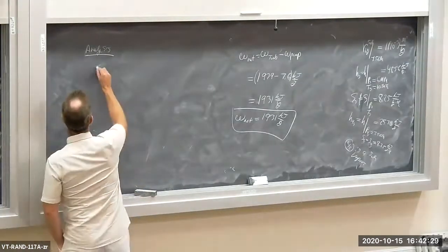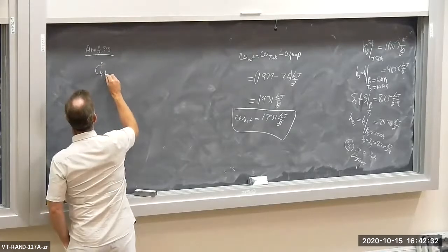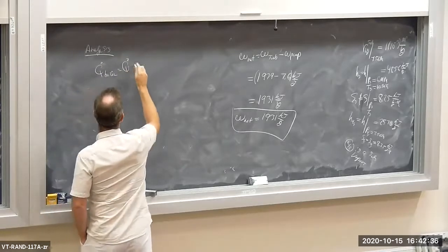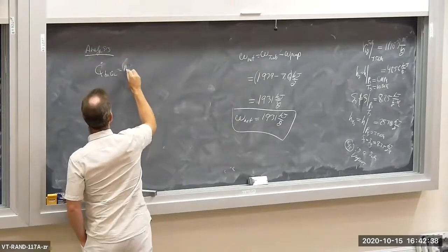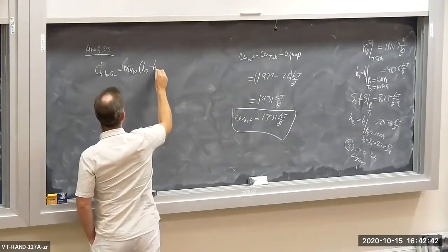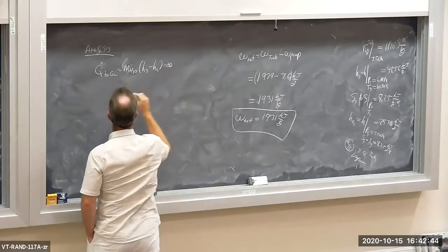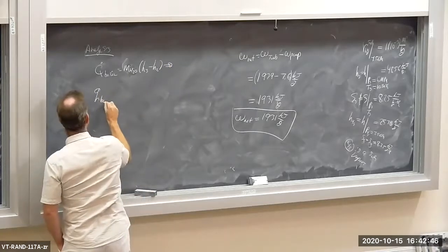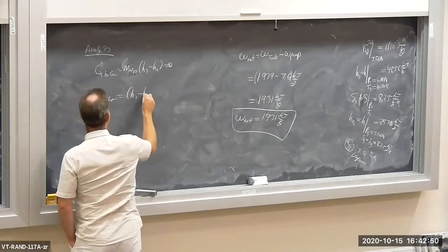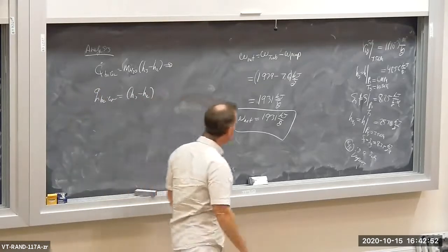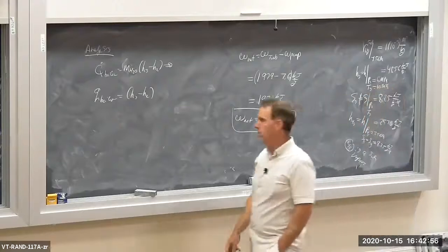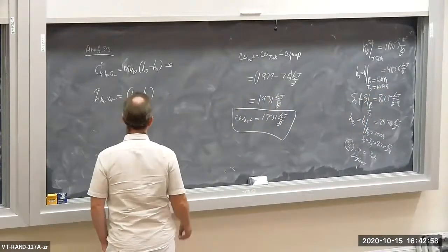I get Q dot boiler equals m dot for the H2O times H3 minus H2, or if you like, Q boiler equals H3 minus H2. Now I have H3 somewhere. There it is, 4856. So what's H2? I don't know what that is.